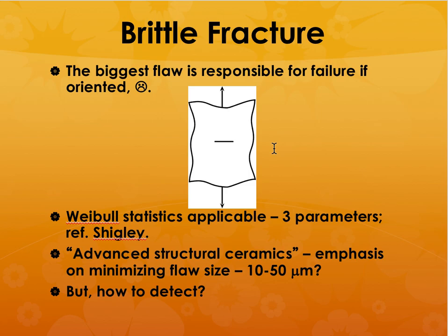And then based on that failure value, you calculate what is called the probability of failure for this material to fail at that particular stress level. If you Google Weibull statistics, how do you get Weibull statistics for ceramics, you can understand that better. Okay, so you rank it and then you calculate the probability of failure at that value.